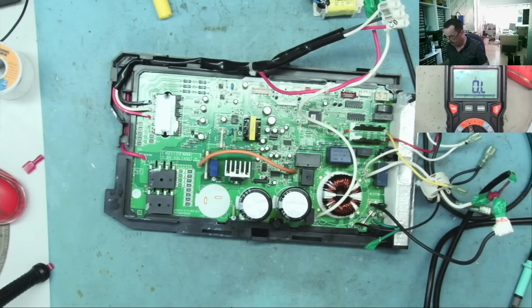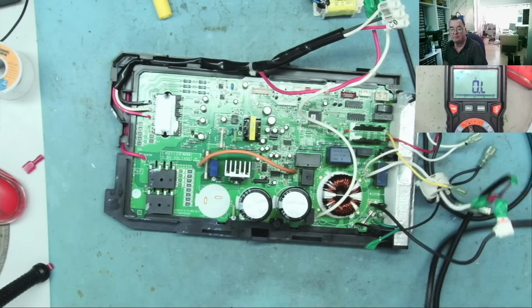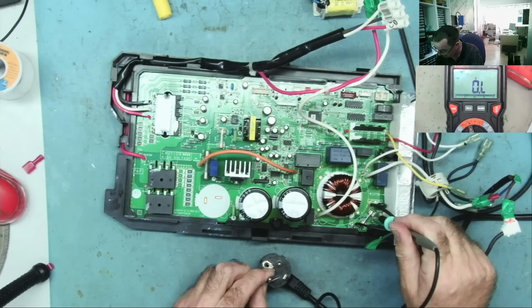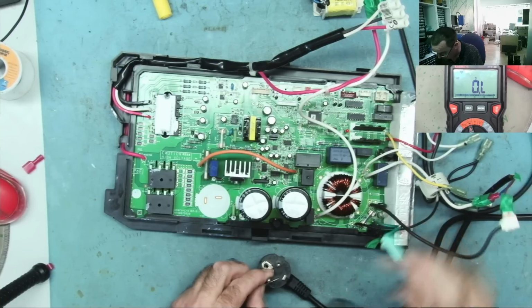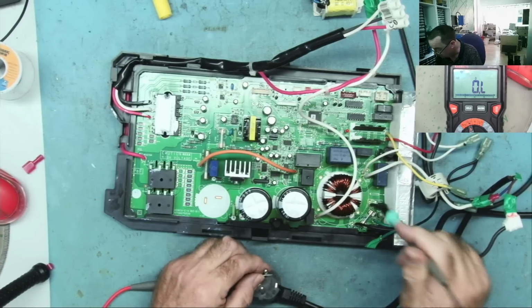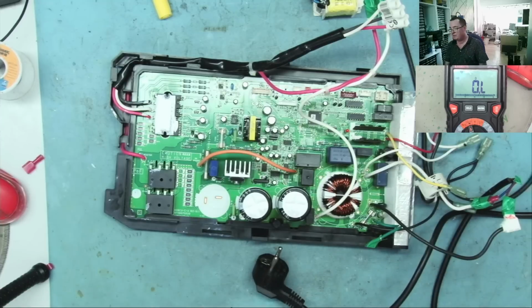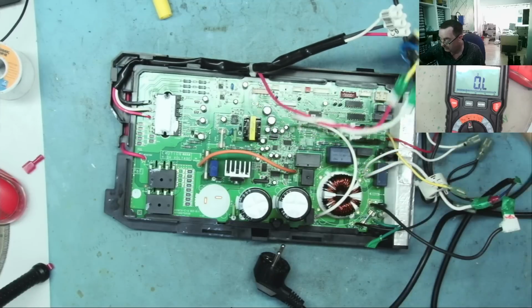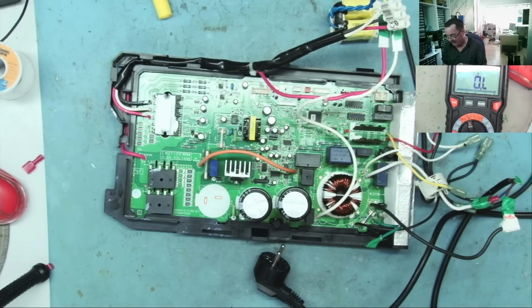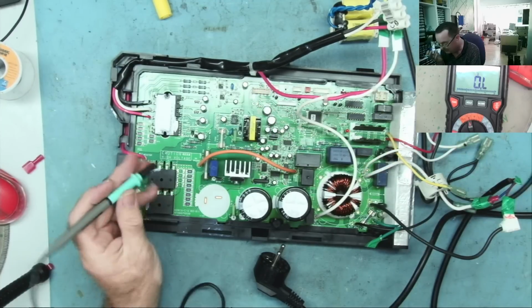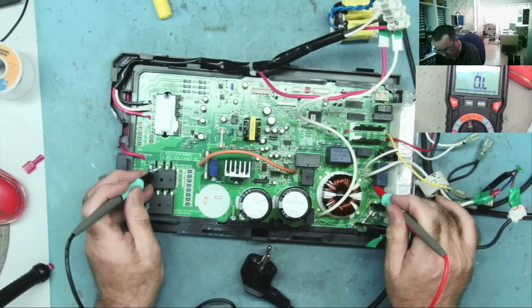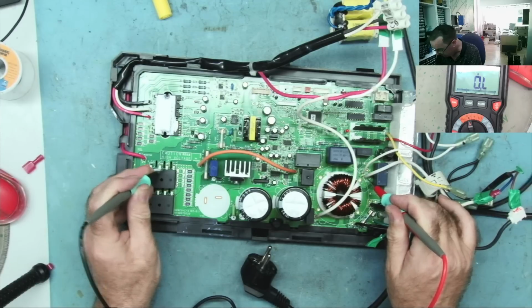Okay, so we can just check this from the power cord. Yes, that's that one, and the other side goes to this one. Okay, so that's connected up. There is my choke. Okay, so again, we can double check. We should have a connection now from power in to one side of the bridge rectifier.